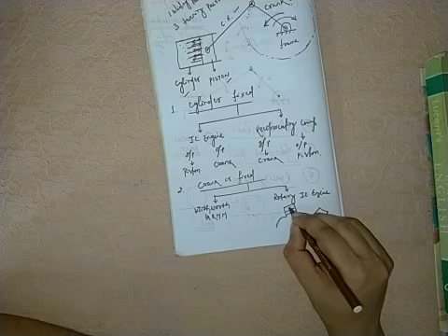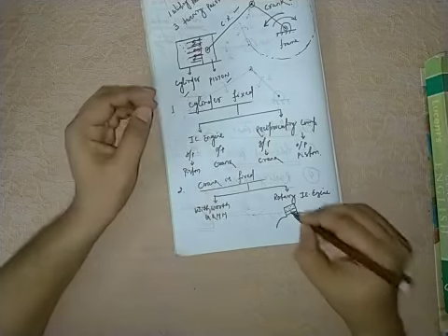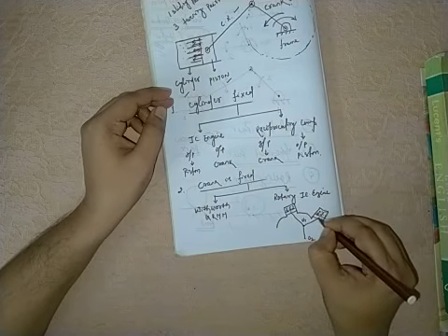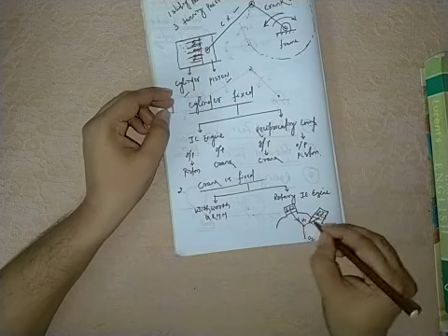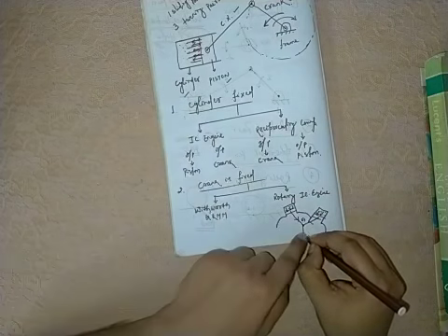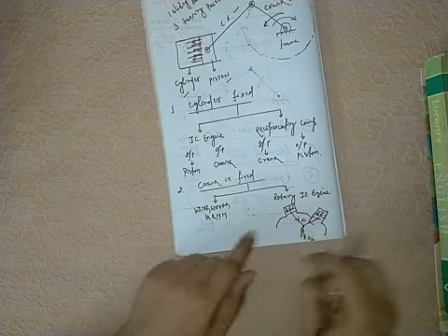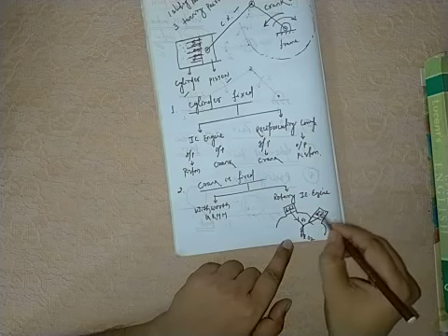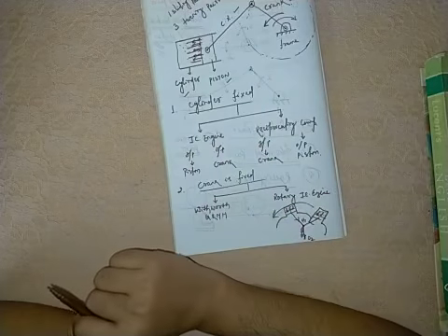Now in this there is gas or fuel which is burning. When the gas is burned, it provides force or pressure to the piston, and the force is transmitted by the connecting rod, and ultimately it will come to what point? O1 and O2. What are O1 and O2? It is your crank. But what you have done? You have just fixed the crank. Actually if it is not fixed, it will rotate the crank. But you are fixing the crank, then ultimately what happens? The torque produced by the force generated through the connecting rod will automatically rotate the total engine. That's why it is called a rotary IC engine.